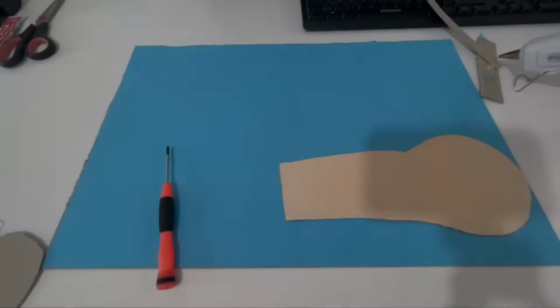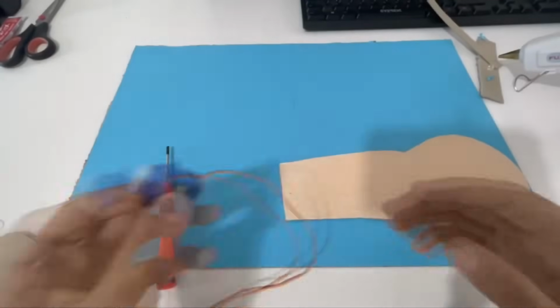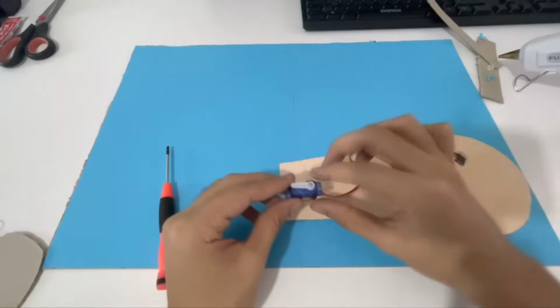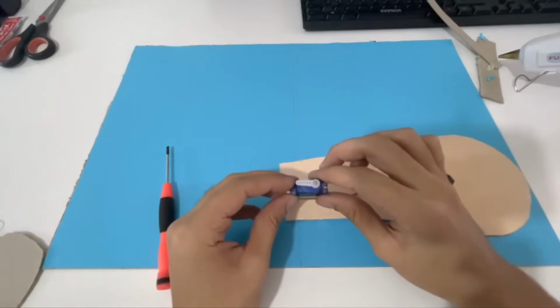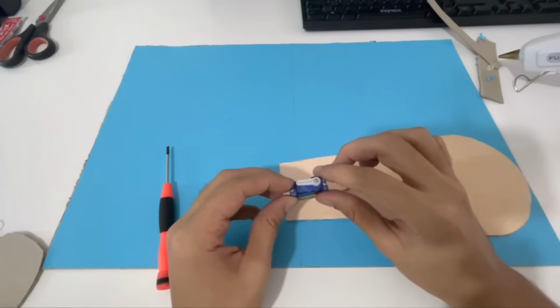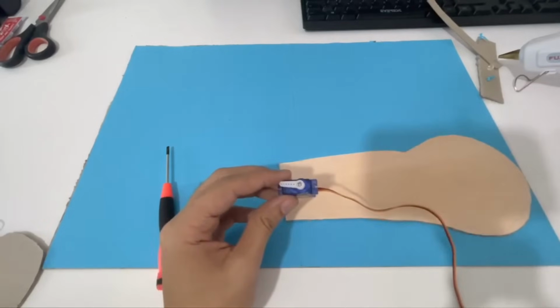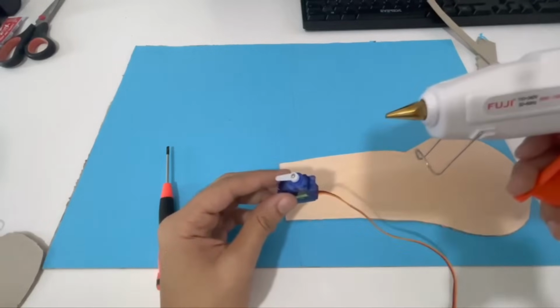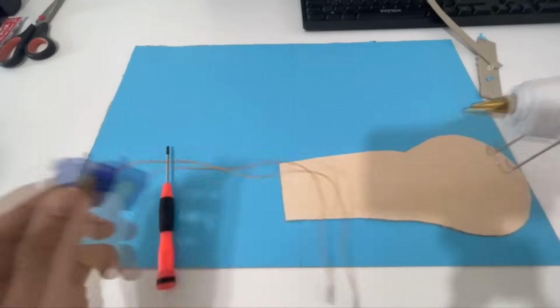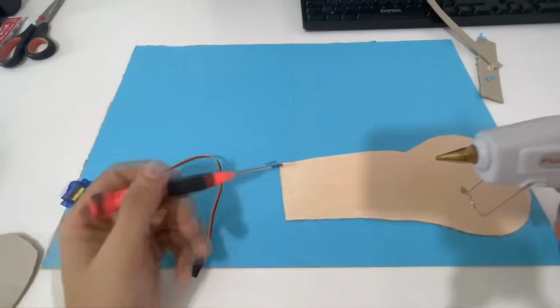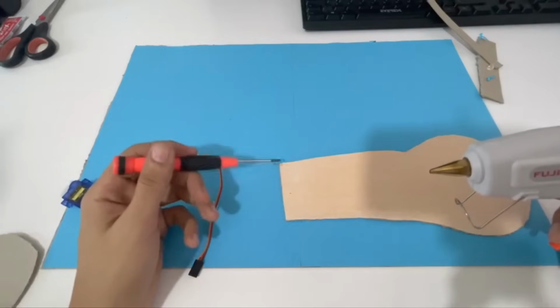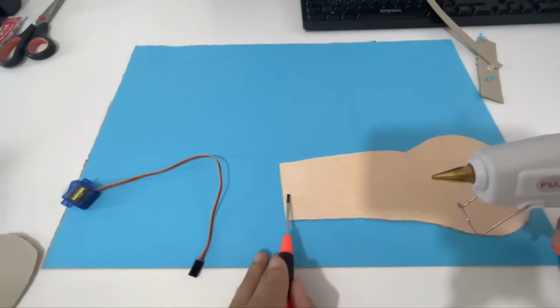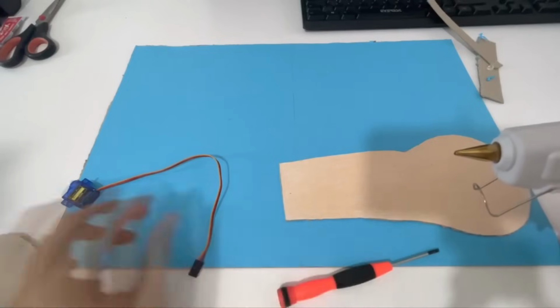Yes my dear friends, in this lesson we will continue from where we left off. In this lesson we will fix our servo motor to our elbow. Look, as you can see here we calculate the midpoint of our elbow. What we need to do is fix our servo with the help of hot silicone. So let's do this operation now. As you can see, the midpoint of our elbow is defined by the blue line.